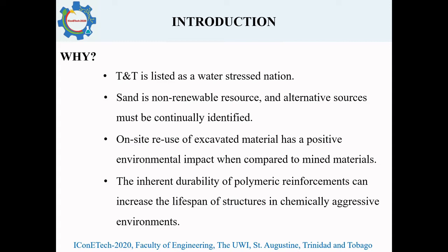Traditional concrete reinforcement made of steel is particularly vulnerable in chemically aggressive environments such as coastal areas. This ultimately has an effect on the durability of such concretes. The introduction of polymeric reinforcements in coastal construction projects can increase the lifespan of these coastal structures.